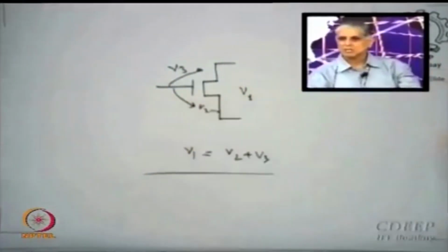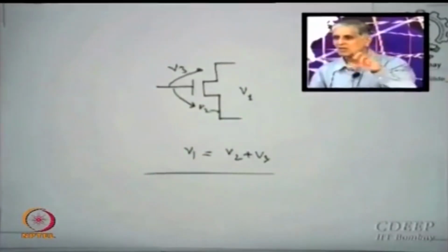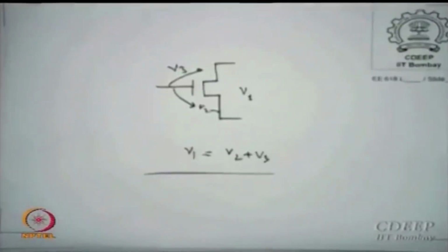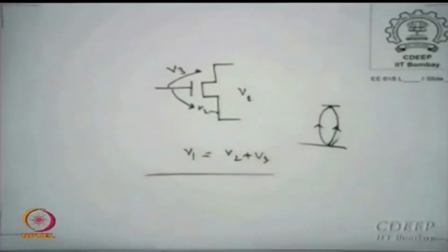So in this technique, please be clear, between two given nodes, whichever path you take, the sum total of voltage must be the same, because between two nodes this is the difference. That cannot be changed. So the method is this or this must be the same; whether you go through this loop or this, the voltage difference is the same irrespective. Okay. So the tricks of the trade is to try games, use whichever value you know to achieve the other one.